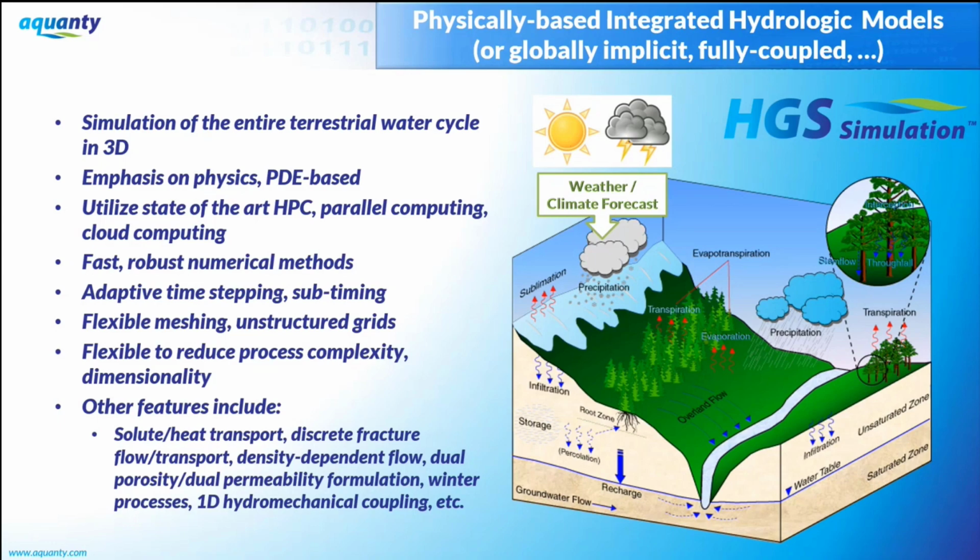So we include overland flow, surface runoff, stream flow, infiltration, exfiltration, groundwater flow, groundwater feeding the streams, evapotranspiration, snow melt, all of these things. And the model is driven by either weather forecasts or perhaps climate projections. Those are the only things driving the model.